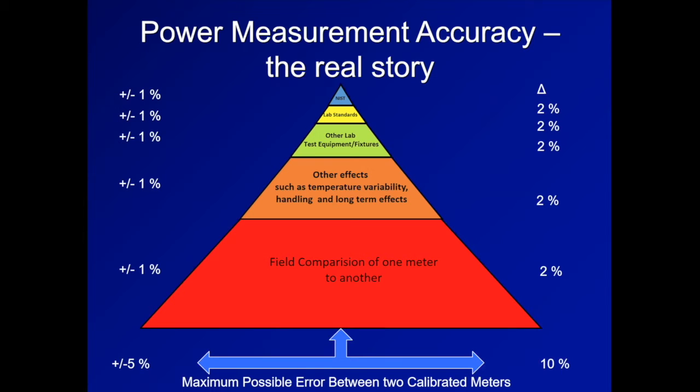So one has to take into account the physical constraints that you're going to use this equipment in. So temperature range, we've tested our equipment from 32 degrees Fahrenheit to say 150 degrees Fahrenheit. We know that the delta in the actual power measurement capability is about 1%. In other words, that's the additional error that you might have over that entire temperature range. Now, typically you don't run into that too much because we're going to calibrate this meter probably at the same temperature, and it's going to be operated within the same temperature range as in your transmitter room.